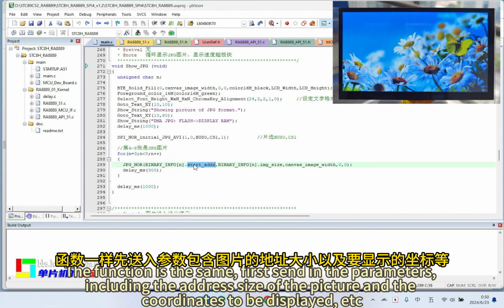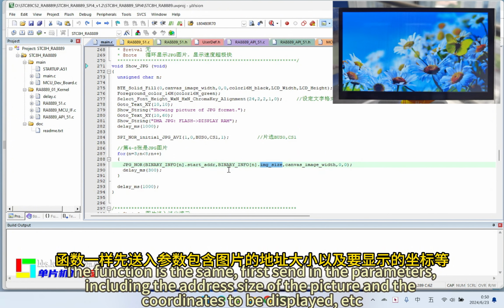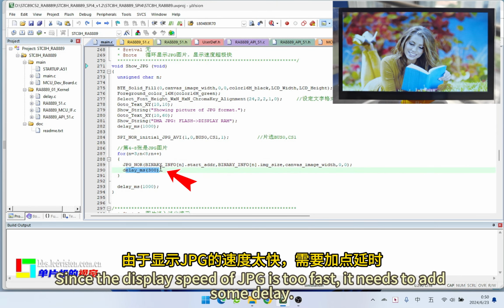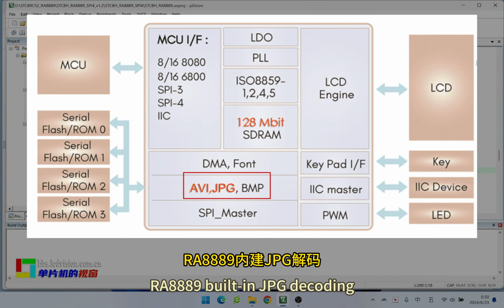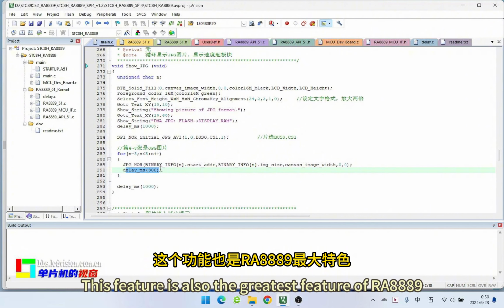First send in the parameters, including the address and size of the picture and the coordinates to be displayed, etc. Since the display speed of JPG is too fast, it needs some added delay. Our RA8889 has built-in JPG decoding. Hardware decoding makes JPG display super fast. This feature is also the greatest feature of RA8889.